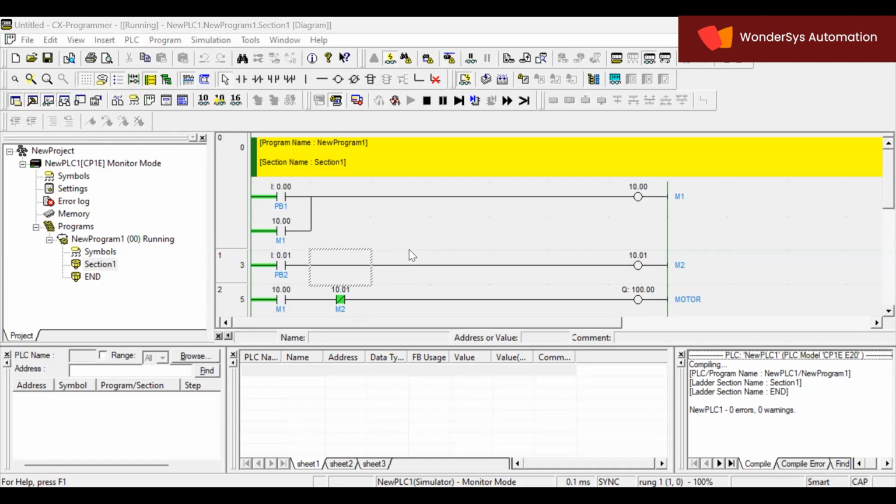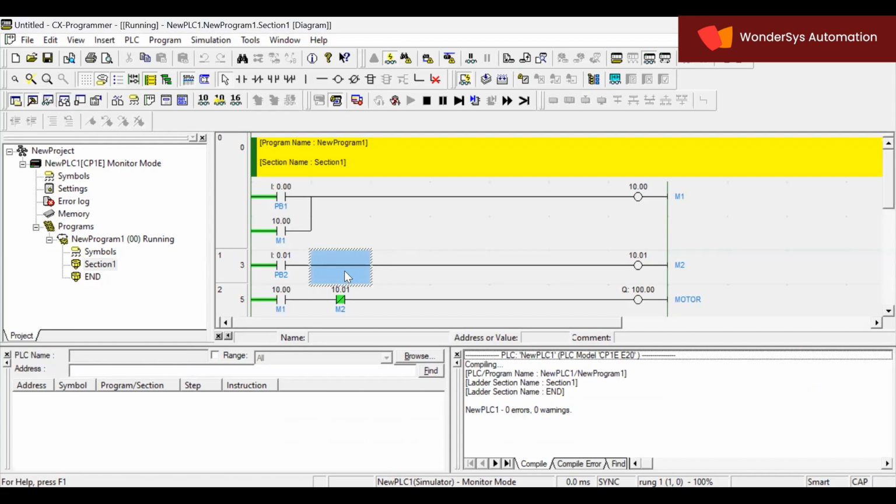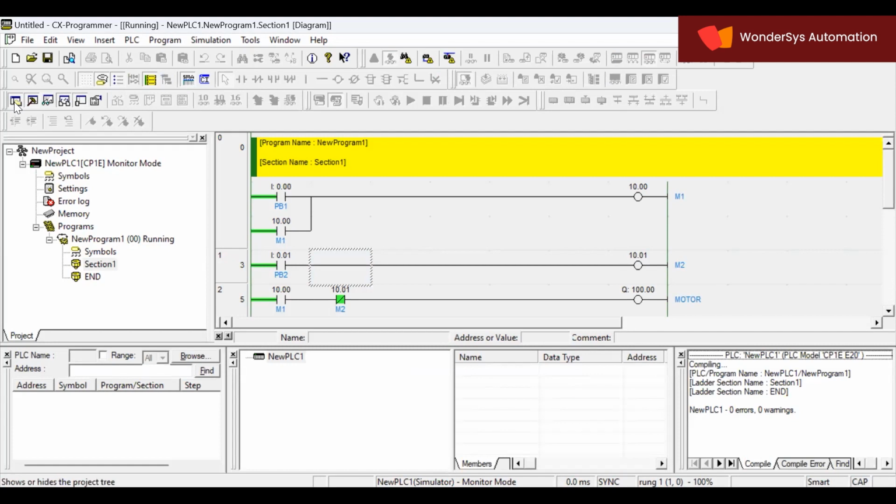No, ma'am. Okay, so the next is set and reset. Here, whenever we are using a push button, we have to do latching, correct? Yes. I have to do latching, then again unlatching, or I have to go for a memory address. So many things I need to use. Now in PLC there is one more option we get, that is set and reset. Okay, one second.